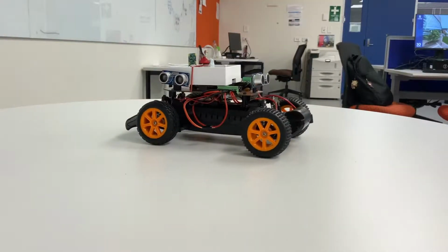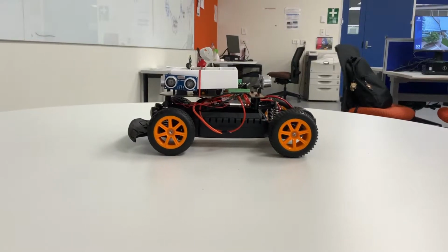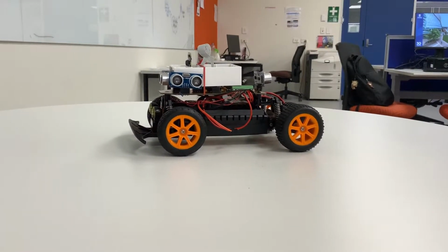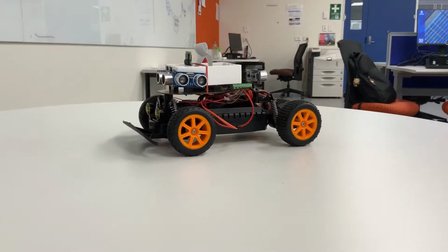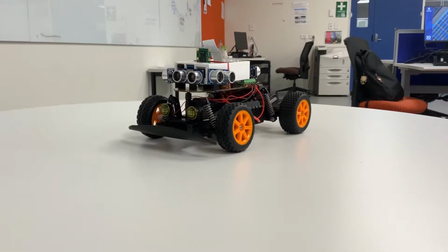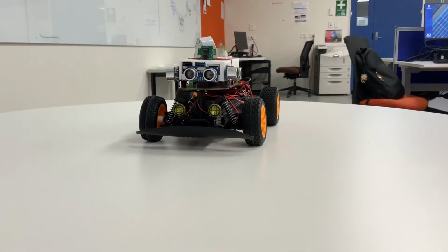In addition to our embedded system, this incorporates range sensors and a motor controller, which are both used for collision avoidance. A Pi camera is also mounted on top of the RC car, which will record live camera footage. Finally, the system incorporates two front LEDs and an LDR sensor, which give an indication of the three modes: collision avoidance, normal, and auto modes.